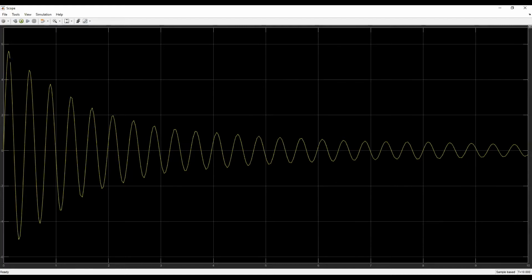What will happen with the load on the needle? When I keep on increasing, the load will also keep on increasing. So what will happen to my DC motor? The RPM is going to keep on reducing. At a certain point of time, the DC motor will not keep on increasing, the RPM will be reduced. So I will change my spring constant, so you can see how it changes.